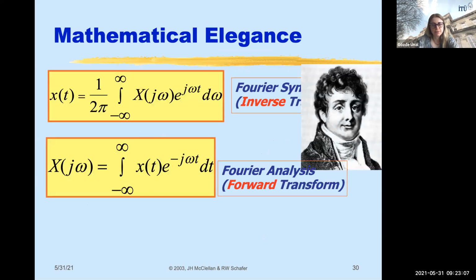So I think, okay, this is summarizing the Fourier transform by saying it's really mathematically elegant theory. We know forward Fourier transform is shown here. We've learned this since last week. Take an input signal in time domain, projected onto this basis function, e to the minus j omega t.